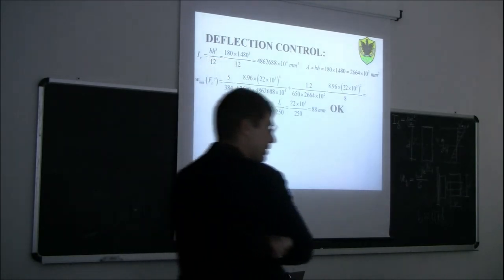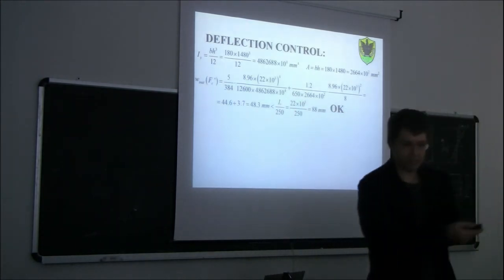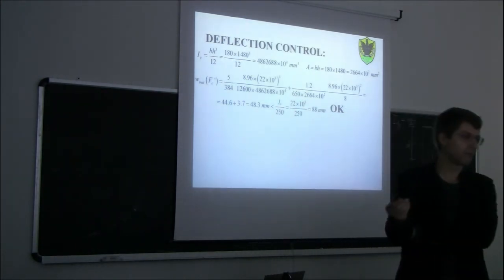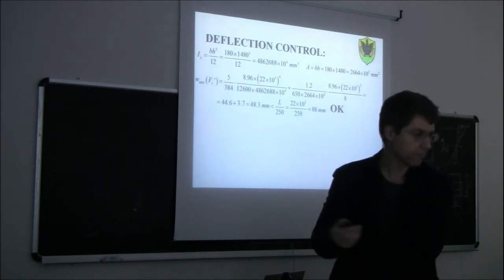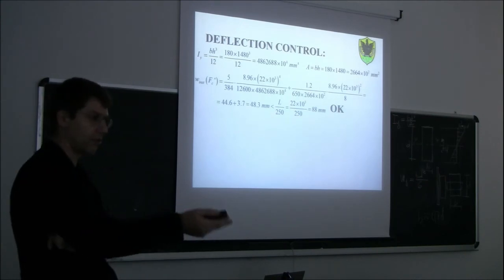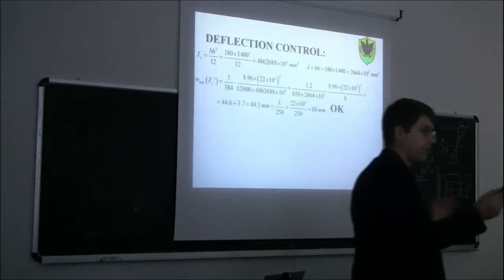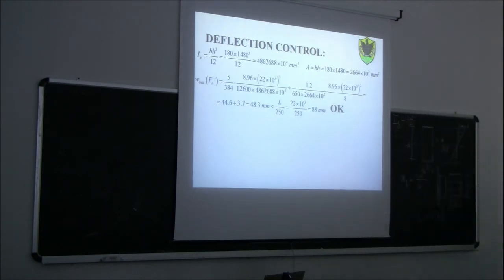Why is it not so important in this case, in your opinion? Because the beam is very low. Okay, because the beam is very low. Like we demonstrated last time, it was also told you by the colleagues from mechanical structures. The shear deflection may be very important when you have a short span beam, not when you have a very long span beam.